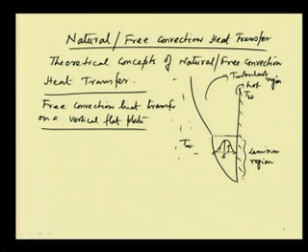Now, what happens here is that this is the hot plate. So, fluid particles coming in contact are getting heated up and they will try to move upward. As we go along the plate, more and more molecules will add to this behavior, and therefore there will be an increase in the depth of the boundary layer. So, more and more molecules will be coming into the picture.